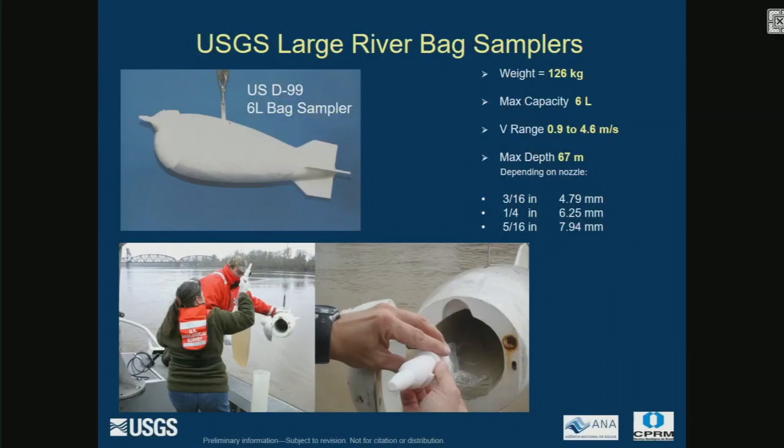I was discussing with Tim earlier that, and I'm not sure how the bag attaches to your MS-8, but it matters how these bags are attached to these nozzles, the nozzle holders. And I am not the best with my fingers, but I can get it done. What you want to do is gather it from all sides so that the opening at the back of the nozzle holder is not restricted with the bag.